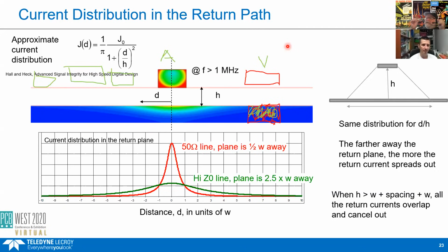And so if I can absolutely guarantee in my design that I'm only going to be looking at the signal during that setup and hold time, and I keep all the switching noise outside of it, I maybe get away with it. It's just a higher risk site.